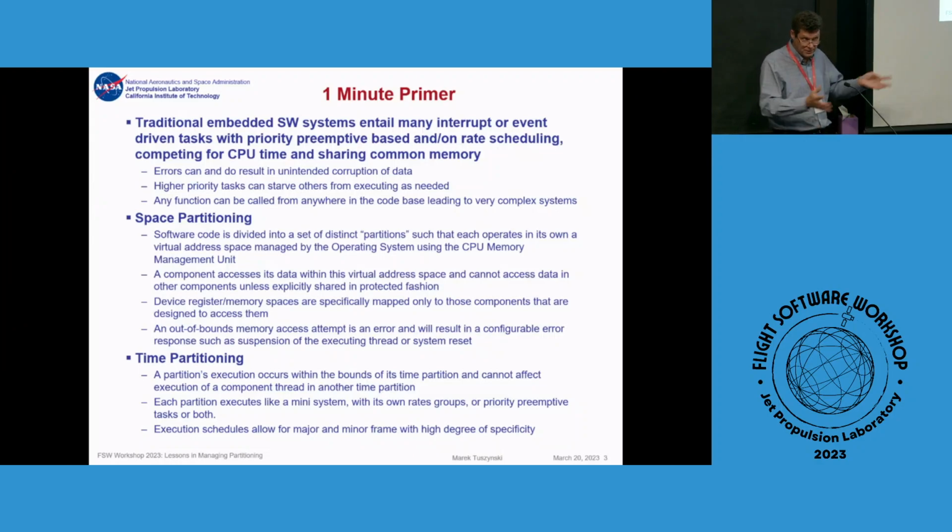So you're sort of seeing a little bit more overhead there too, because now you might have a 16 hertz rate group in one partition, and then you do the same thing in the next one and the next one. So there can be overhead, and that was one of the concerns. But essentially, each partition is independent and guaranteed by the RTOS to be able to run no matter what's happening in one of the others.